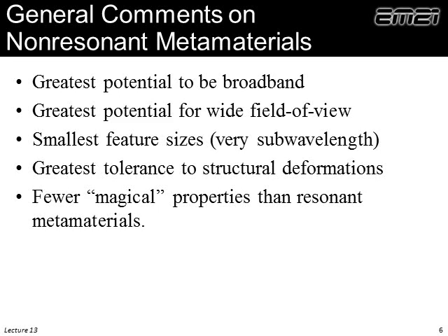I do want to mention some benefits of the non-resonant type metamaterials. Other than the hyperbolic metamaterials, these really are not getting as much attention in the literature, but the hyperbolic certainly are. That's an exciting area right now. But I think these have the greatest potential to be broadband simply because they work from DC up to the cutoff, and the cutoff is where it starts to look like a photonic crystal, where the lattice is becoming resonant.